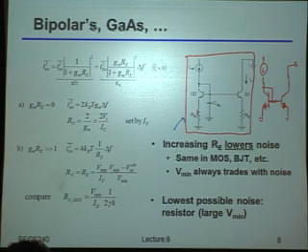So what's happening in this bipolar circuit here is that you add this degeneration resistance just to reduce the effective GM coming from those bipolar current sources. Now, I'm not going to walk through the math because it's not particularly important. But what you can see is that even with this source-degenerated version, there's still a direct trade-off between the minimum voltage you can tolerate across that current source and its effective noise resistance.